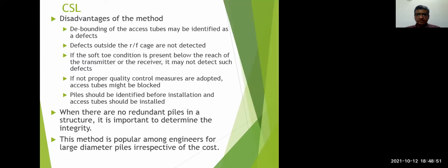That is because this probe is about 150 millimeters in length. So it will not reach the center line of that, and the bottom 75 millimeters are not scanned, but that will give us an indication, because if there's a defect at the toe, then before that, it should indicate that.